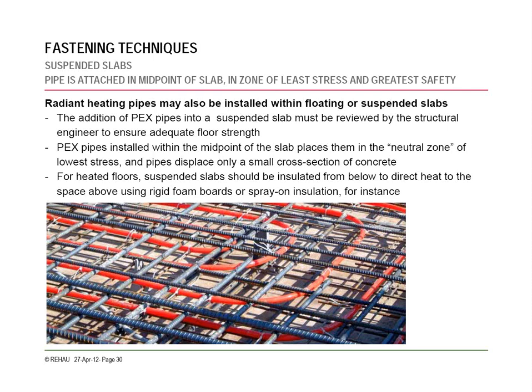And depending on if you're using it for heating or cooling, you have to be cognizant of the space below, either putting up foam board below it or spray insulation, unless it's intended to heat both ways. On a lot of new projects where they're using them for heating and cooling, they'll be putting the PEX in the floor and ceiling slabs, and basically it's using it to offset the heating and cooling in both zones to bring down the heating loads or cooling loads.